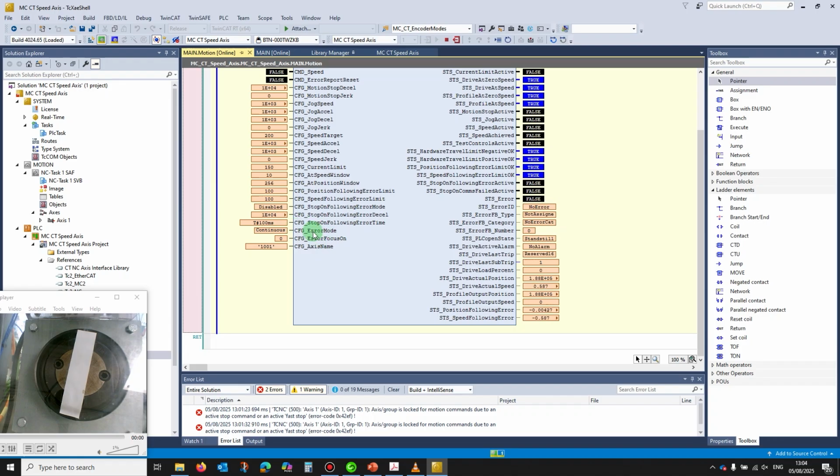Next, you've got the error detection. So inside of this block, we're actually using the normal function blocks like MC_Power, MC_Jog, MC_MoveVelocity, MC_MoveRelative, etc. And in order to be able to collect all of those function blocks together, you can imagine that there's error outputs for each of those individual blocks, and you've got to do something to be able to collate all of that information and put it out in a meaningful way.